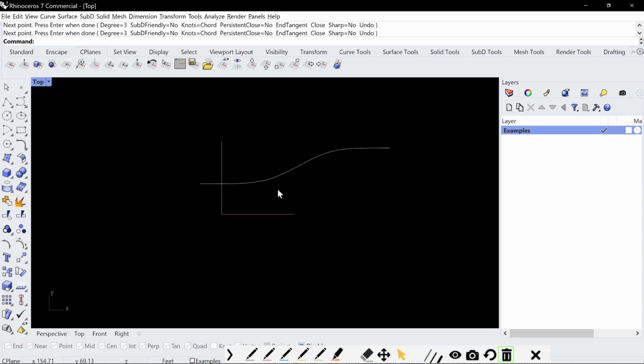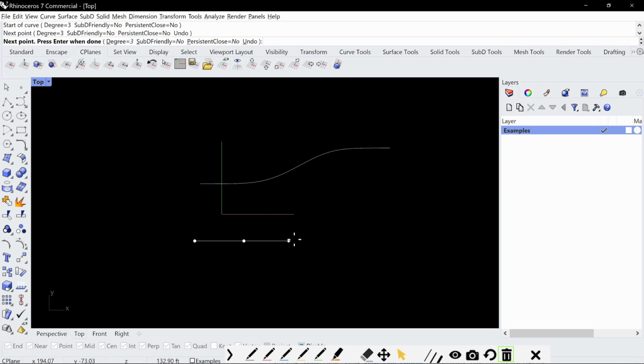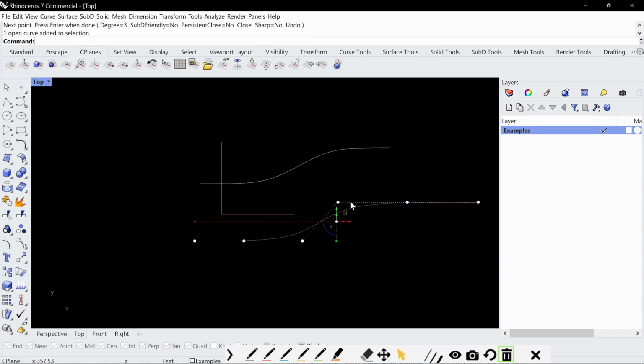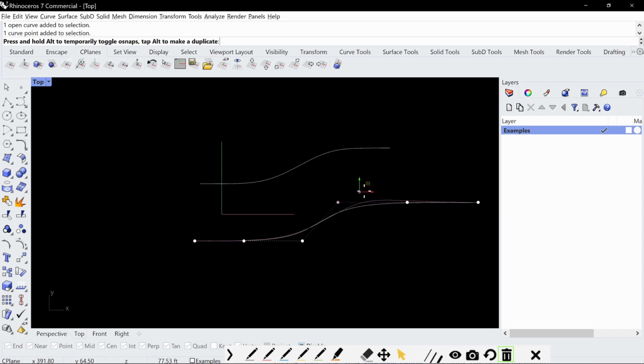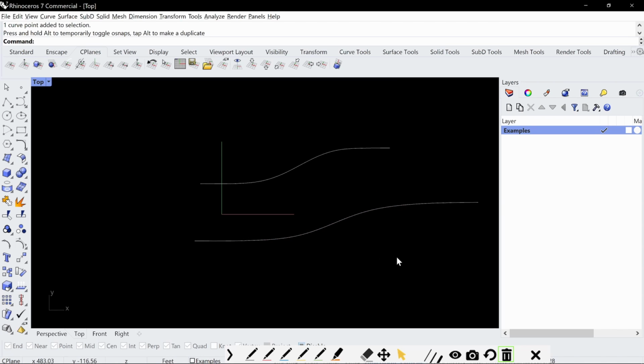So curve, you want to go between the two and see. Typically, people will do control point curve because you can use fewer curves and really define the geometry that you want by using not as many points. And it's actually best to not have as many points as possible because it starts to add to your geometry.